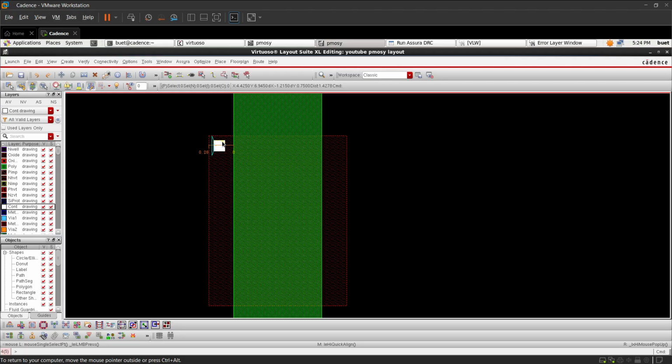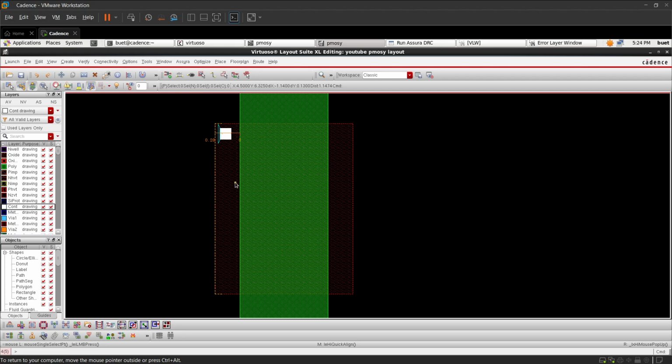Why are contacts going to be made? Because whenever you are supposed to take a connection from any of the terminals, let it be source or drain, there should be a contact, right? Because without a contact you cannot interact with the material that has been inserted into it. If you want to give any supply, you have to give the contact. Only through the contact can you connect your outer source to our PMOS design.